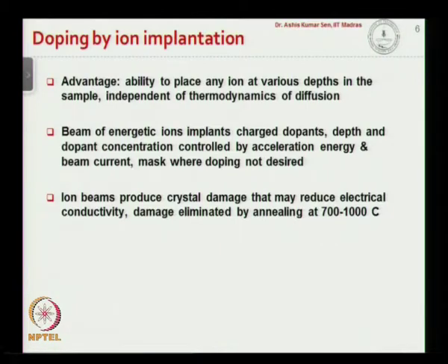Now another approach to do doping is by ion implantation, okay. So by diffusion based doping, always the concentration of the dopant reduces with x, and if you want to dope at a particular depth, it is not possible, it has to always start from the surface and go into the depth.